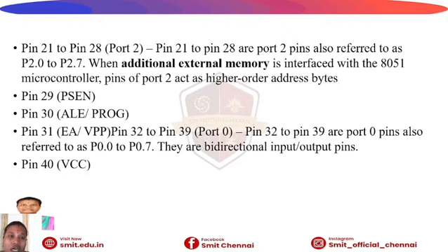Pin 31 is the EA pin. EA stands for external access input. And pins 32 to 39 are port 0 pins, also referred to as P0.0 to P0.7. These are bidirectional input and output pins. And the last pin, pin 40, is the voltage pin, VCC.